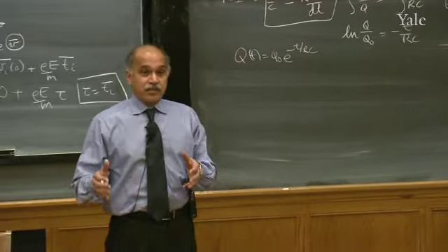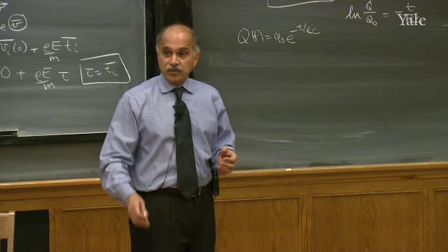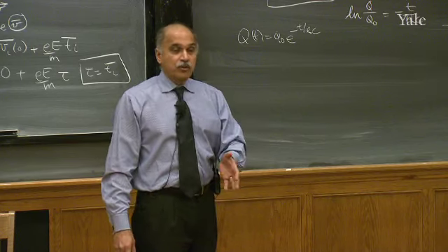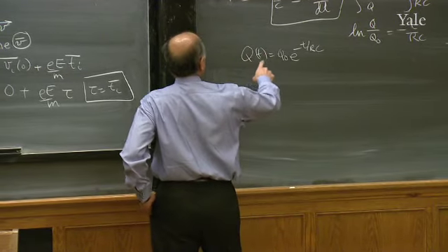But sometimes you want the decay to be very, very slow. People are even thinking of getting rid of batteries and just buying capacitors. With a capacitor, you can use it to drive something, but slowly the voltage will go down. So if your device can operate over a range of voltage, the voltage is just Q of t divided by C. That's the voltage at a given time. If you can operate between that voltage and that voltage, you can run it for that time. Okay, so this is the fate of the charge.